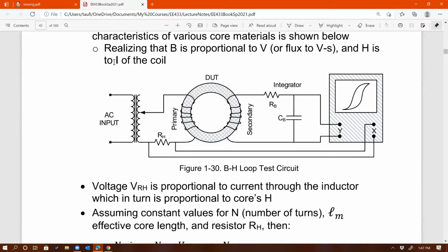So we should be able to measure current and then somehow transform that data into the scope. And again, scope is typically measuring voltage, so I'm going to convert that current into voltage. But that should not be a problem, right? We can use Ohm's law to convert current to voltage. Okay, so that's what you see here in this circuit. This is the basic configuration of that circuit. In the lab, you'll see the more practical, or more realistic circuit to do this.